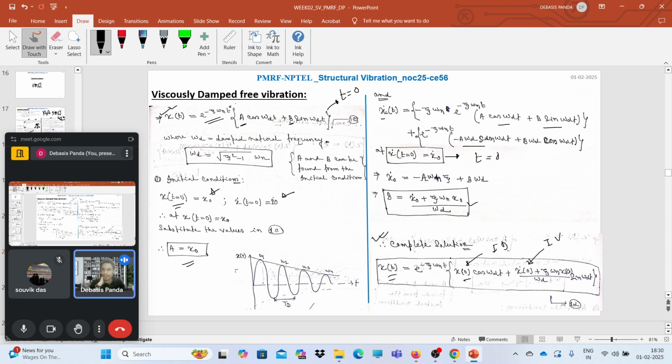Right, now look at this, damping is present. What damping actually does is reduce the amplitude of the vibration. Here we have provided some initial velocity and let the system vibrate. We can see that the envelope is dictated by the term e to the power minus zeta omega n t. How much your zeta is will dictate the slope of this curve.